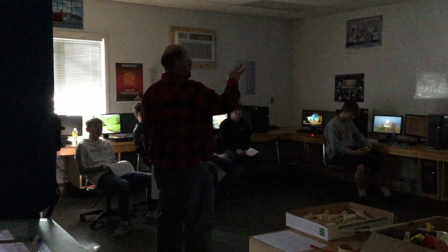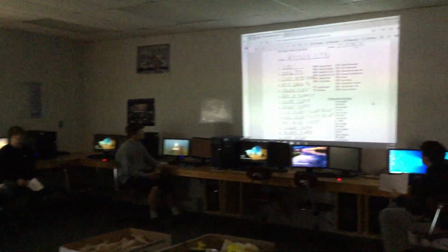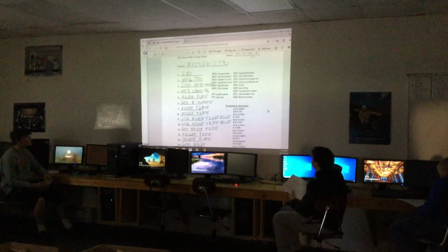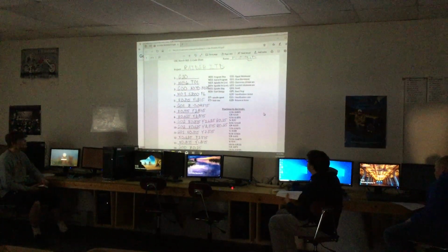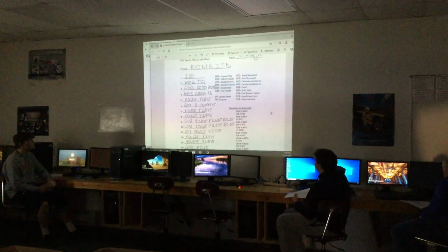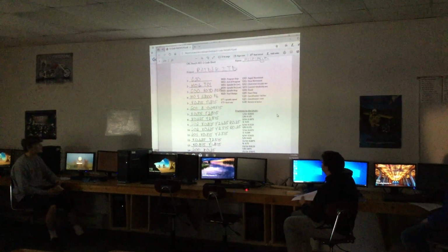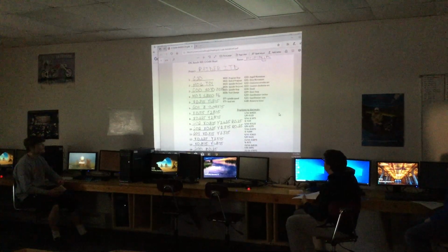Okay, so what am I doing at number 3? Rapid movement. That's important to understand, that G00 and G01. G00 is rapid movement, so it's going to move a little faster. And then G01 is a slow movement. Why do you think they have those two different?